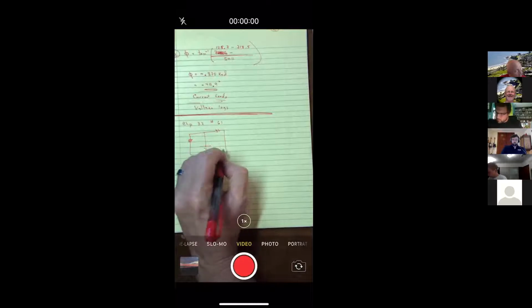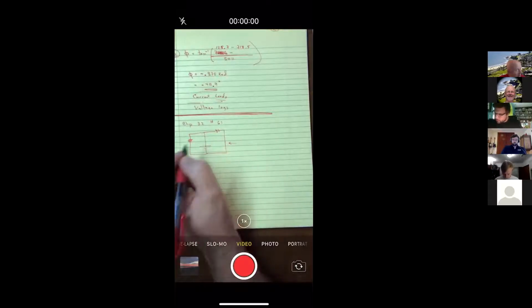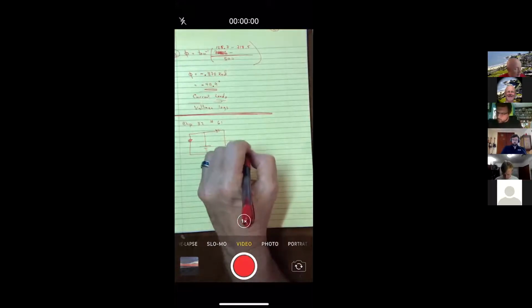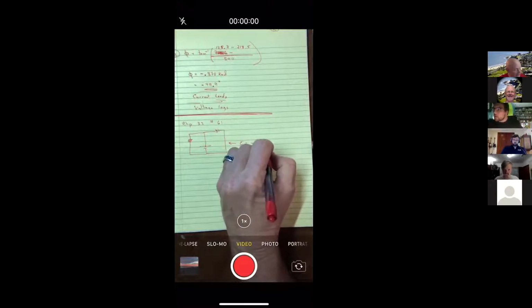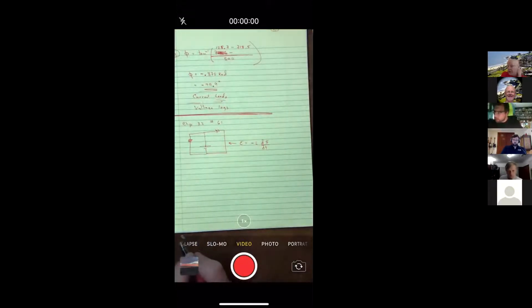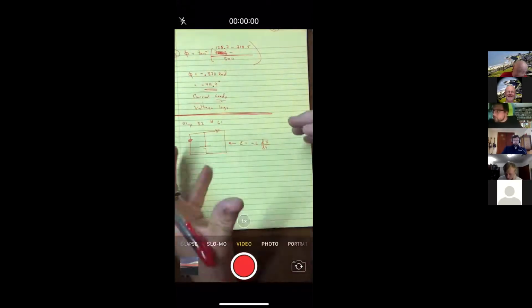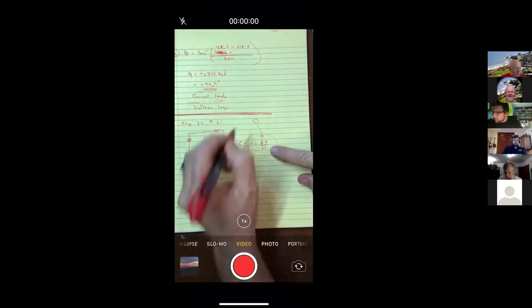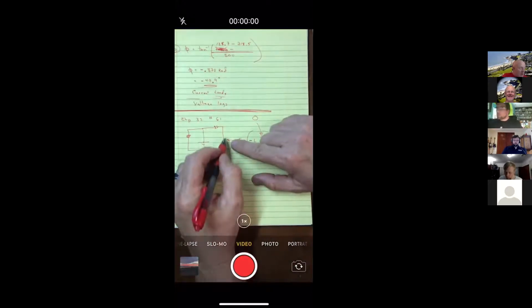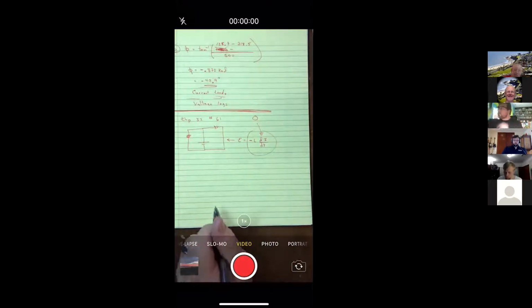But this is the part where I'm thinking that right here, I could ignore the inductor. Remember that the voltage on the inductor is minus L di dt. And so if you didn't catch this in chapter 32, when we have an inductor in a DC circuit for a long period of time, there's not going to be any more changes going on. We can safely say that there is no voltage change on the inductor, which is the same as you get for a wire. So after a long period of time, we can just replace the inductor with a wire.